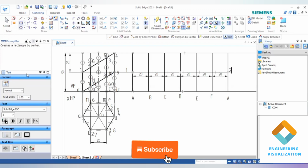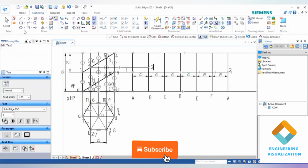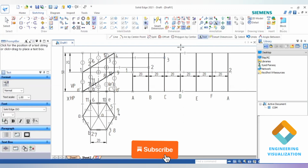In the same way, the projection of a horizontal line from 2 till B, that is your point number 2. Now projecting point number 3 horizontally till the vertical edge C here. Now point number 4 exactly falls on the corner point of the vertical edge D here. So we can mention that is 4 here.